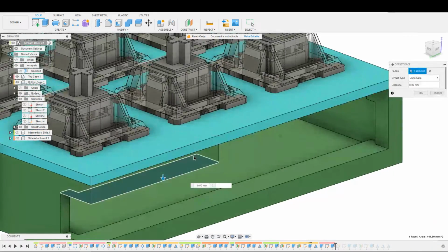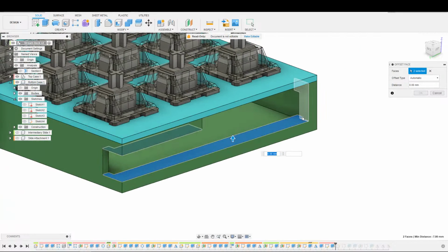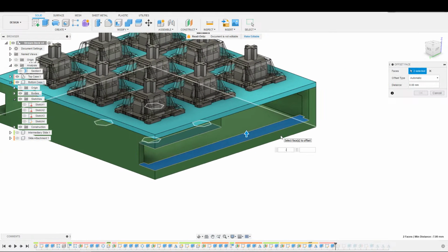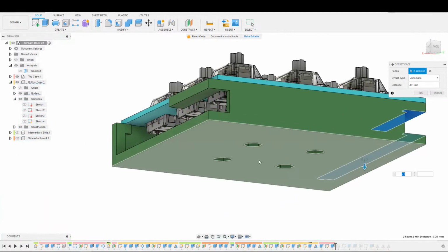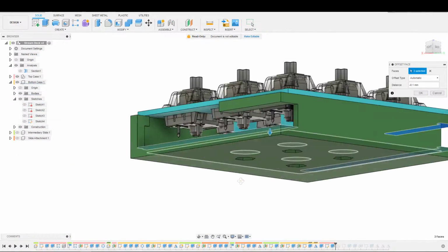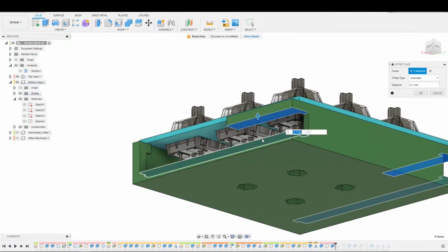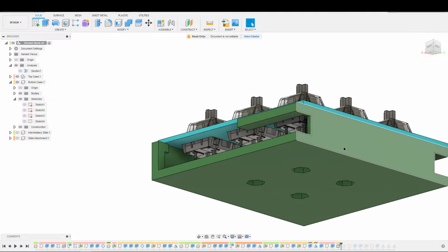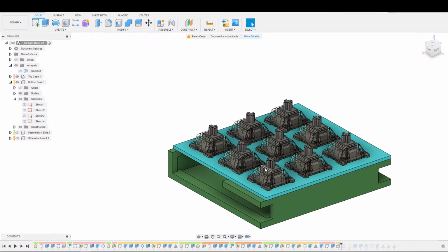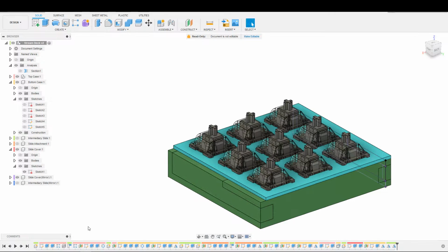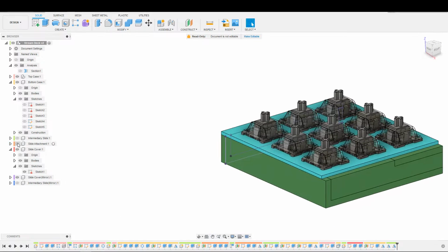So we need that and that to give this slide clearance. Minus 0.1, let's say. And again, I'm doing this before I do the slide cover, because the slide cover wants to be whatever this is. And this is new. Minus 0.1. So the slide cover I still want to fit in there, which means that I wanted to take into account those offsets.